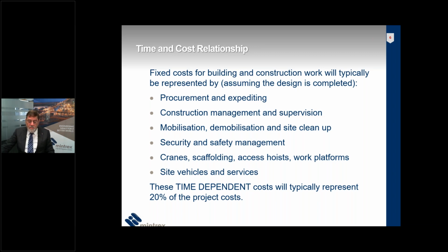As we've all been told many times, time equals money. Typically in construction work, fixed costs represent at least 20% of all costs, and that'll be made up of MOB and DMOB, your cranes, your scaffolds, and your general access ways, security and safety provision, management and supervision, procurement and expediting, and the site services that are required from before the day you start until after the day you finish.